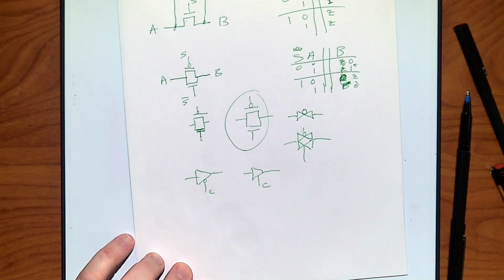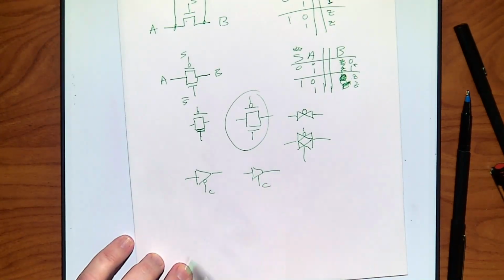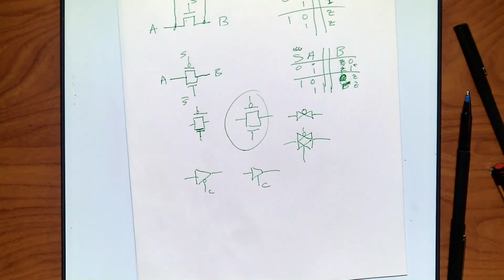And the third state is Z. I just make or break the wire, connect or don't connect the wire. Right? Similar here, except you're just saying high is open. So it's really just which way you hook a transmission gate. This is really important because it's used for a number of different things, one of which is buses, which we've already talked about. This is a great way.